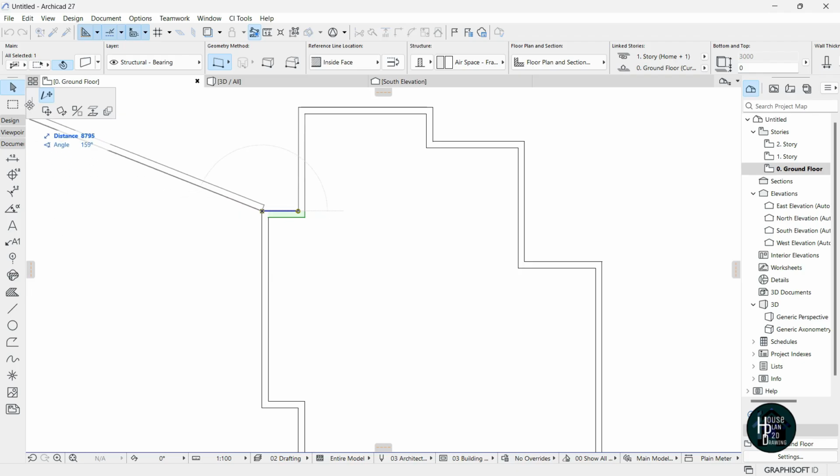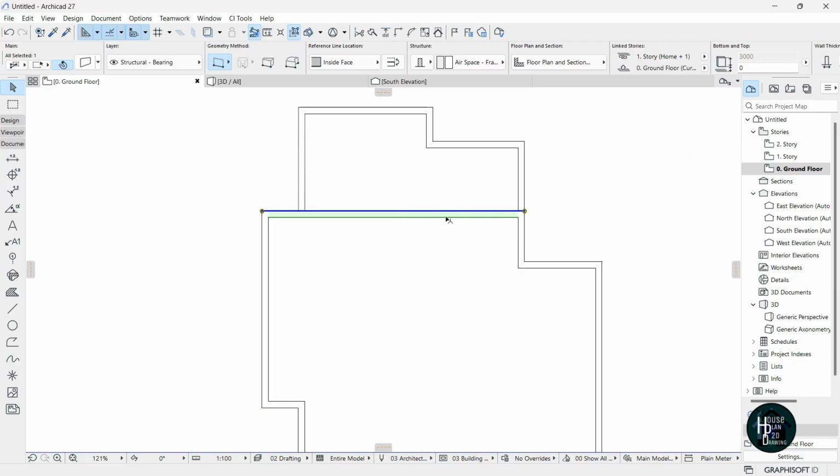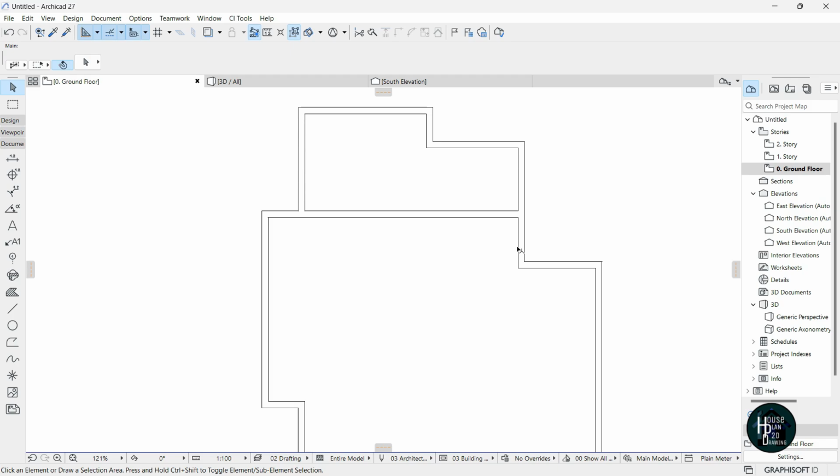You can start to move your cursor around this angle here, click, and you can drag it to any position of your choice. Once you click the node, this box is going to appear and it's going to ask you, maybe you want to stretch the wall, drag the wall, rotate the wall, mirror the wall, elevate or multiply. But for this node, I only want to stretch. As you can see, stretch is selected, so I'm just going to stretch it to this side here and click. Once I click, I'm going to have the design come outside like this, and now I'm going to press escape on my keyboard.